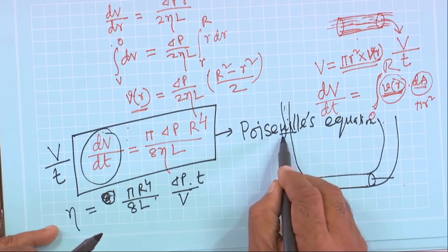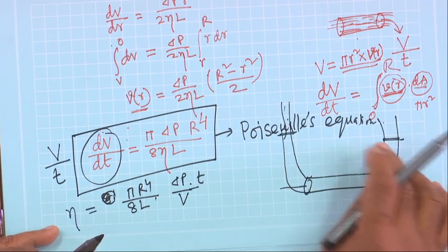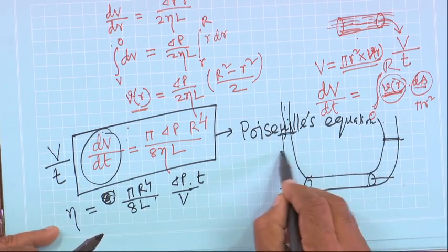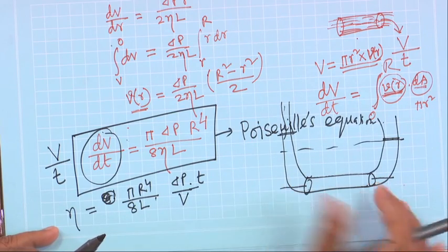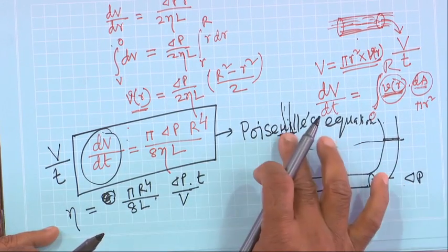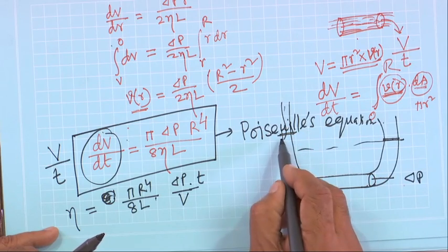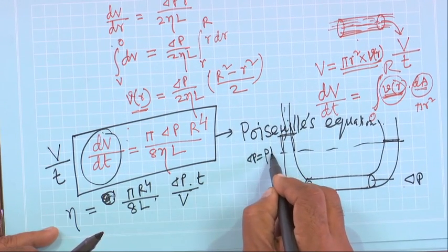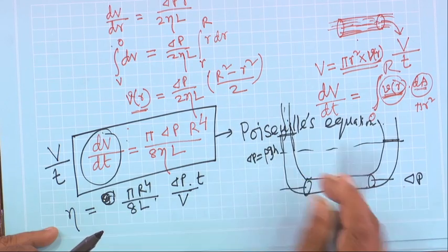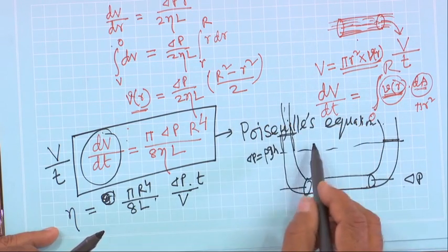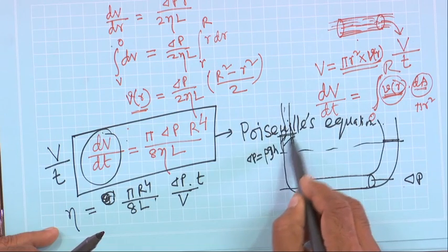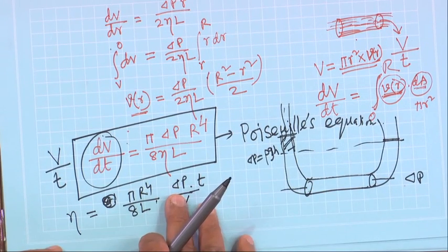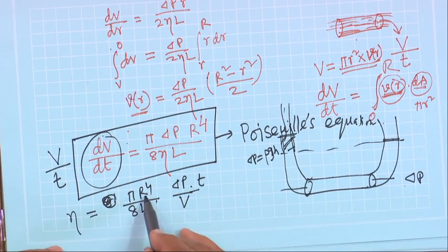Depending on the liquid height difference, we create this pressure difference del P. From the manometer we can take this reading. So, this del P will be actually rho g h, where h is the difference of these two water levels.